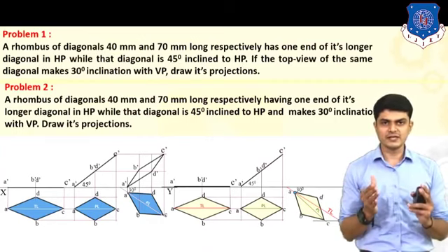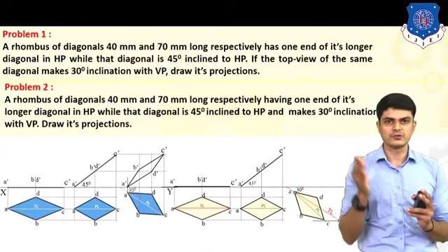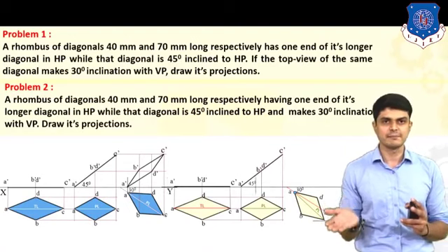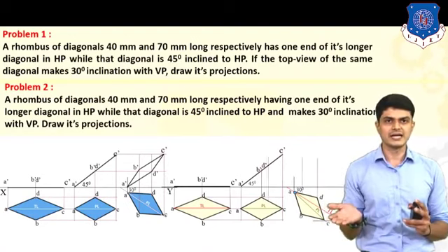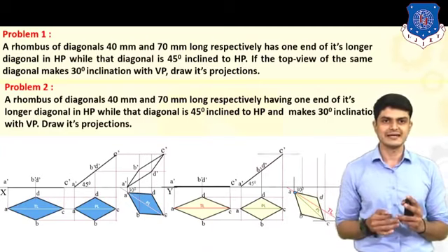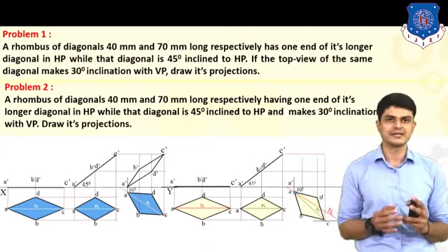Now, after drawing this figure, let us move ahead and find out the front view in this vertical plane. So we must draw the vertical lines from each and every point like this. So let us draw a vertical line from each and every point. Then after, let us draw the horizontal lines from the previous inclined line. So we will be drawing the horizontal line from the previous inclined line.